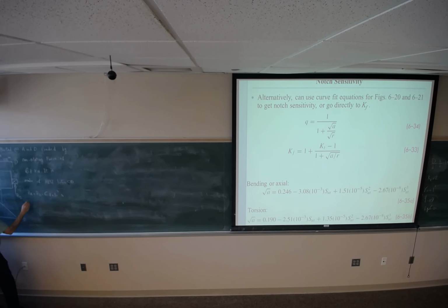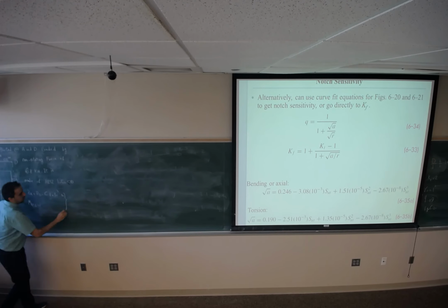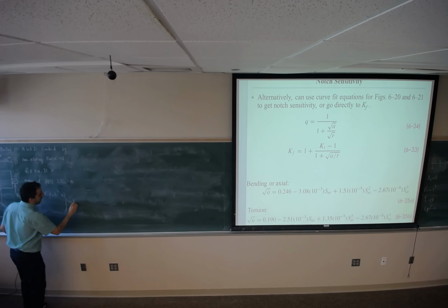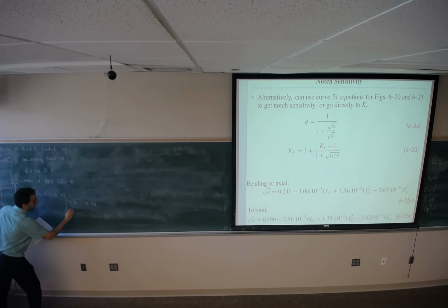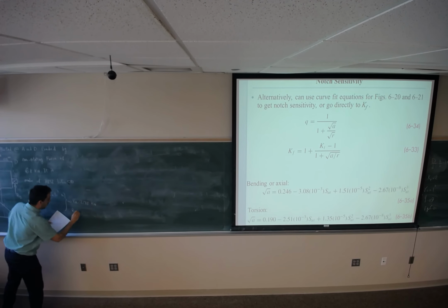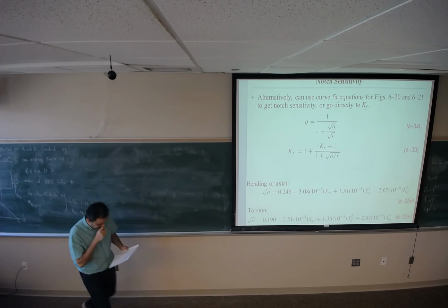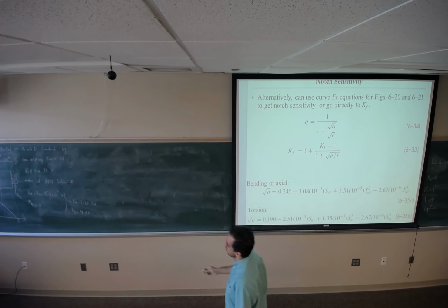Also, the bending moment at either point A or point B should be 0. These two equations give me RA equals 2.78 kilonewton and RD equals 4.018 kilonewton.